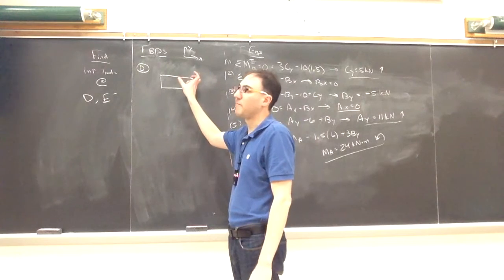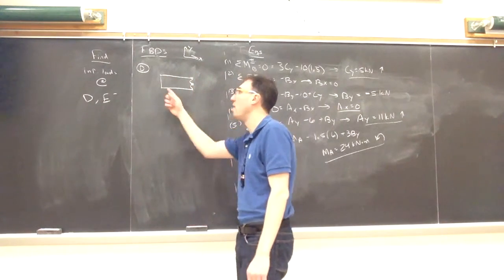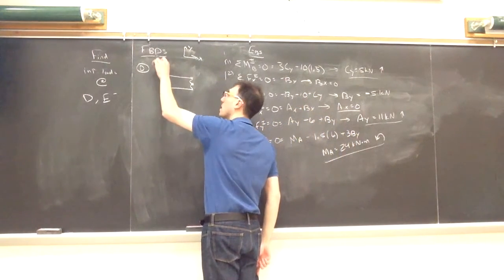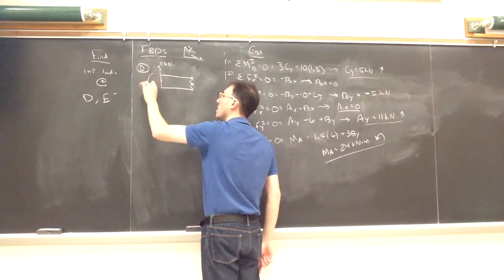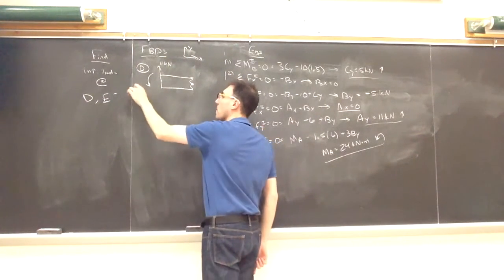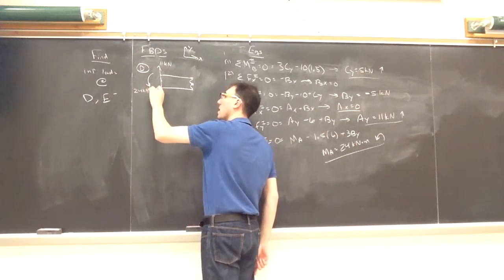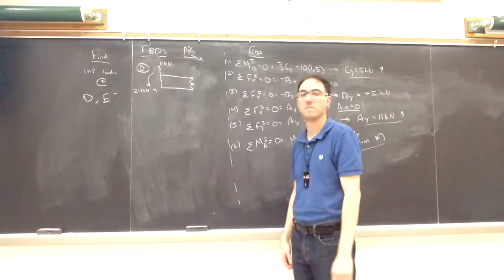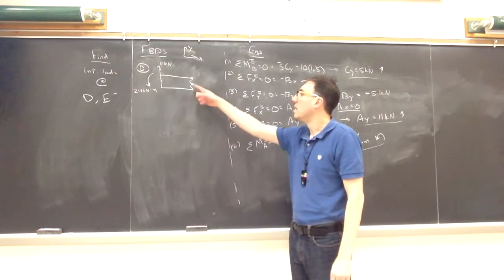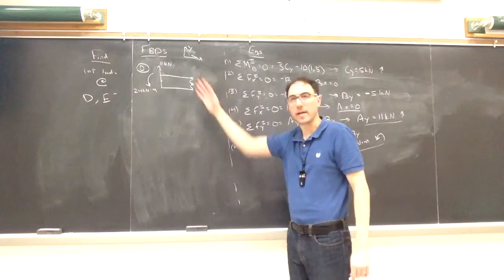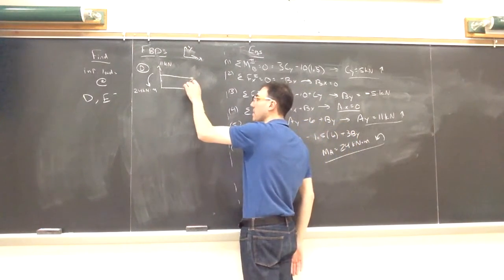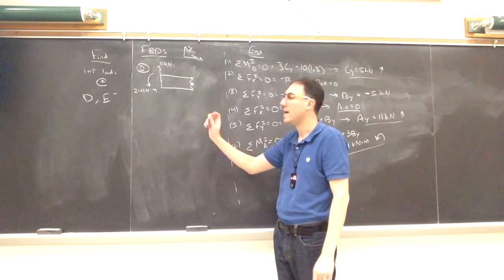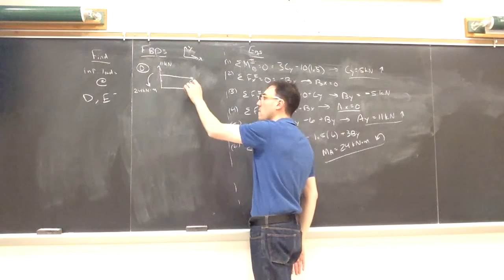On this piece of beam that goes from A to D, I have all those reactions at A that I found before, 11 kilonewtons up, the moment of 24 kilonewton meters acting at A. Ax turned out to be 0, so I just won't draw it in this picture. I'll jump to what's happening at the point I cut. So at the centroid of this beam, which I'll just draw as being in the center, I don't have enough information to actually know exactly where the centroid is, so I'll just model it here.